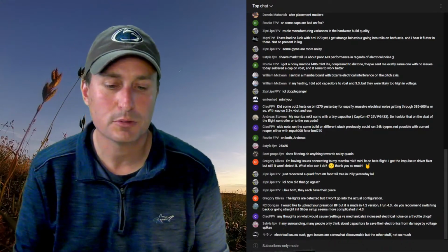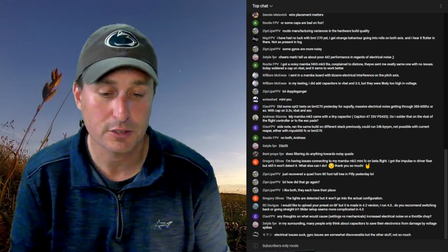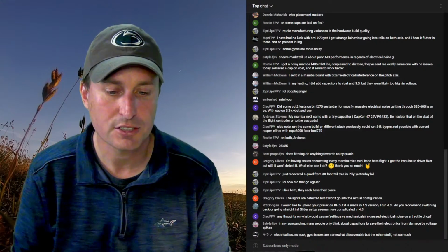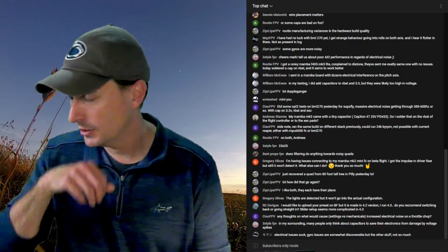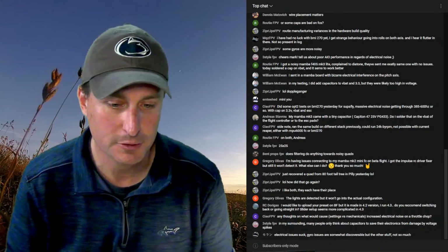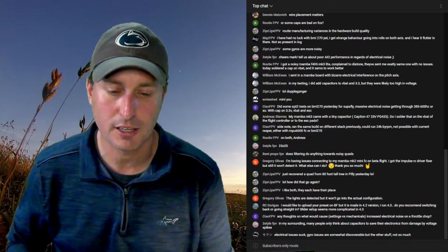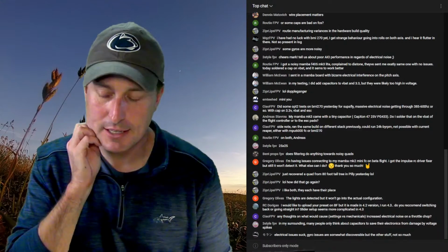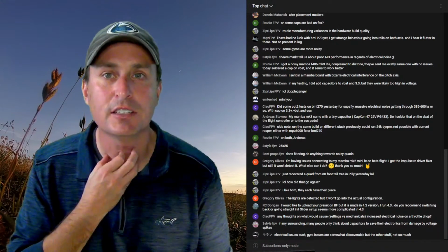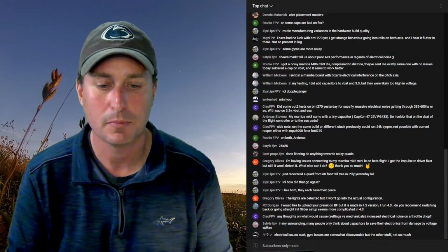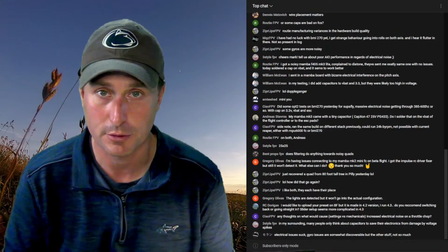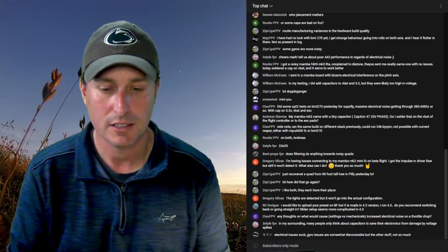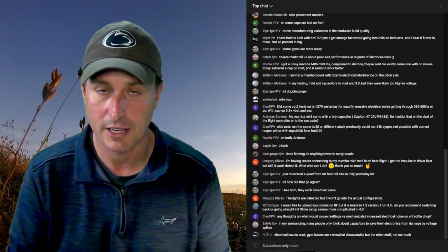So you're saying you tried to flash or connect your flight controller to Betaflight and you're having issues. You tried the Impulse RC driver fixer, and that did not work. What else can you try? That is the easiest one. If you have an opportunity, one big thing you can look at is hooking up another flight controller, if you have one. Does that work? If it does, then your driver should be okay.